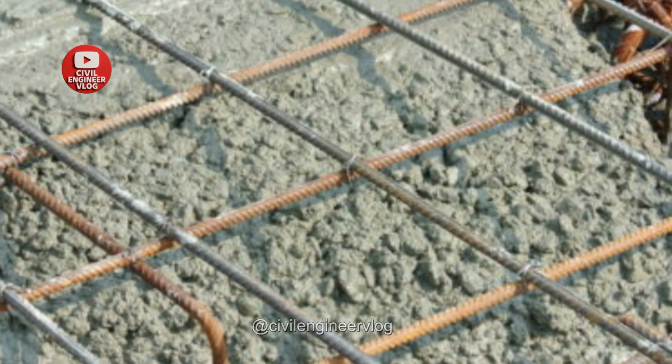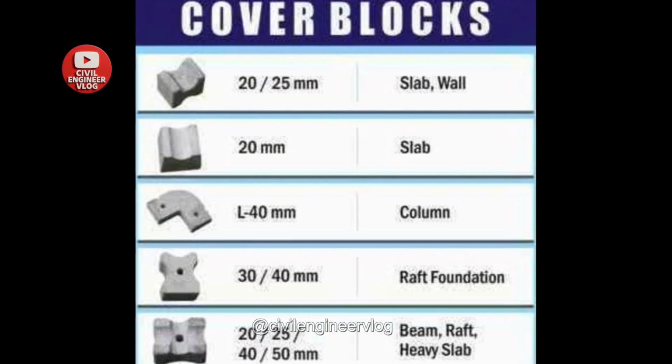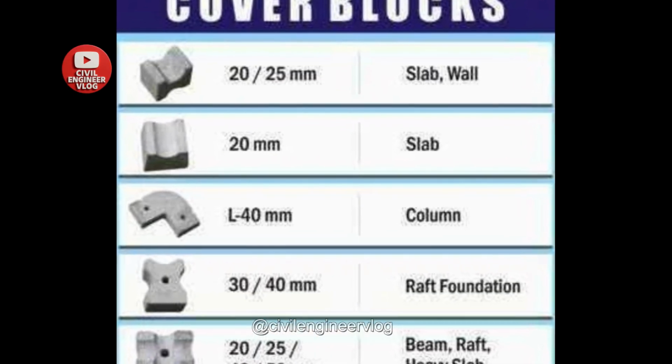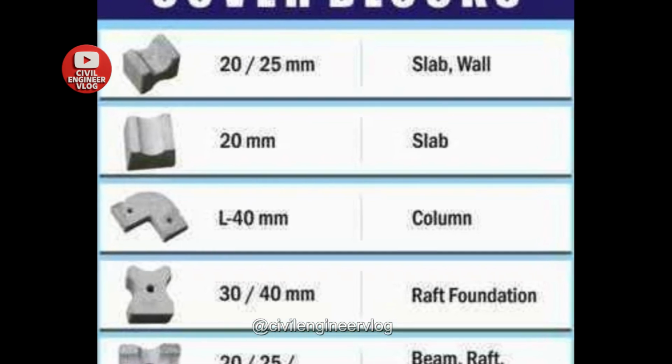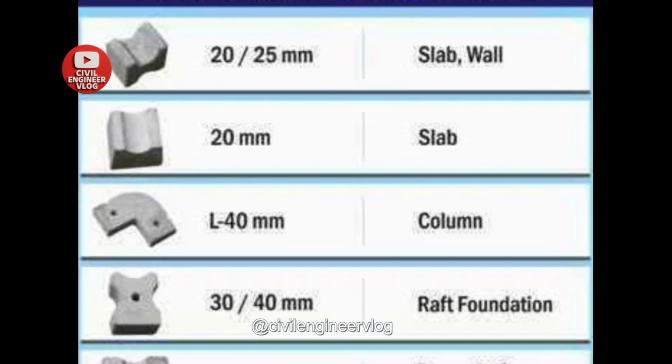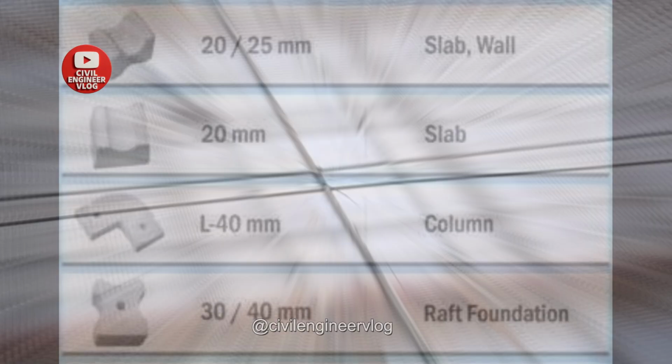Provide minimum cover as per standard. Column 40mm, beam 25mm, slab 20mm. Always use concrete cover blocks, never use bricks or stones.